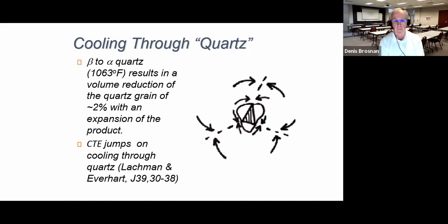So we heat up the quartz. The quartz goes for a ride as an accessory mineral through the kiln. We might get a little bit of surface vitrification there. And so we're going to get about 2% expansion or thereabouts on heating. On cooling, remember that the vitrified material and residual clay particles around that quartz granule solidify. At certain temperatures, they solidify where the glass solidifies once again, but the quartz hasn't gone through its beta to alpha inversion.